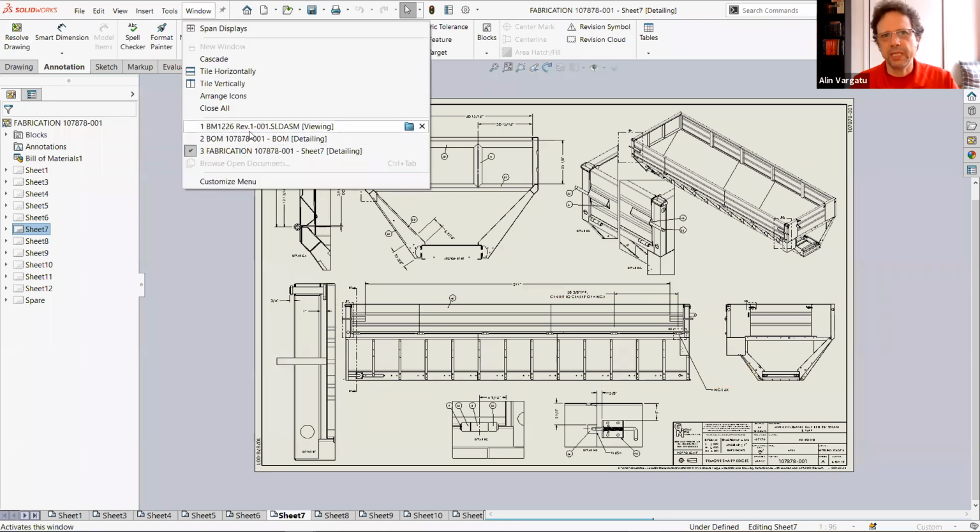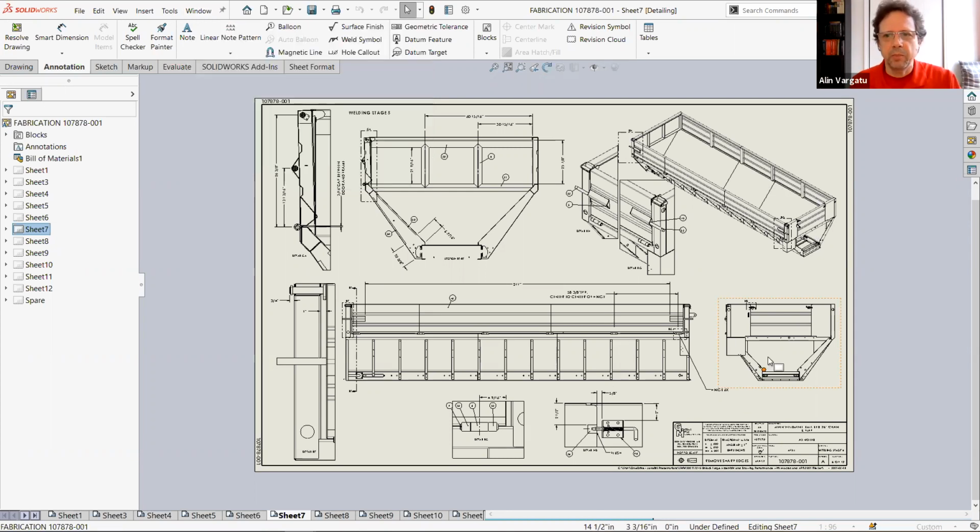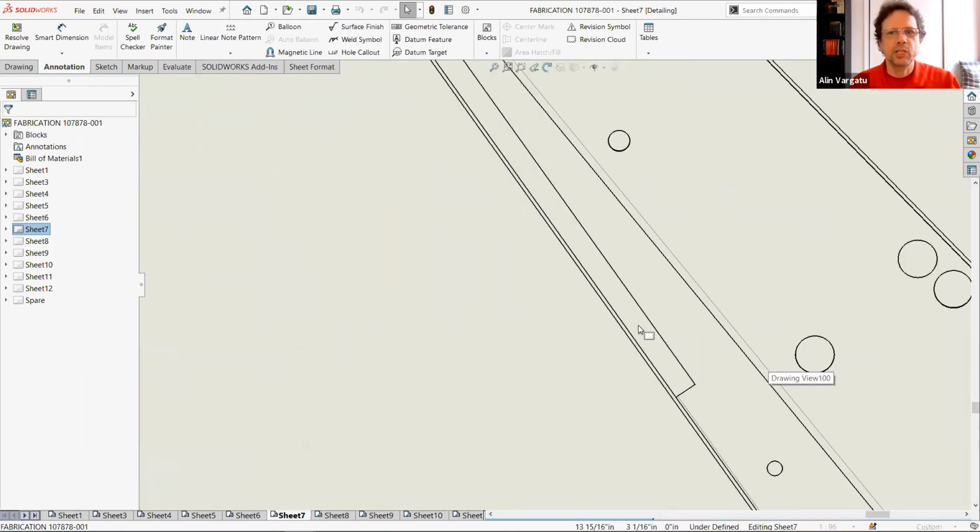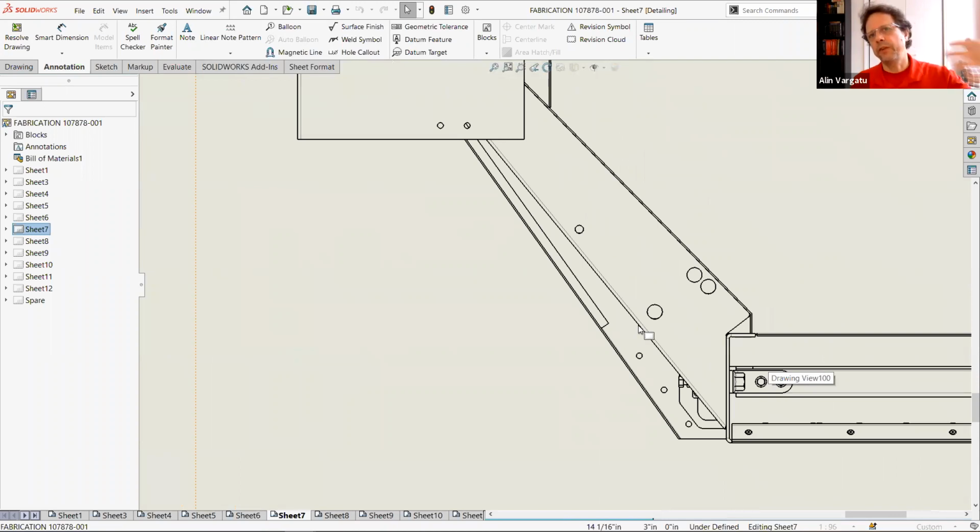So right now, even though you see the top level assembly, which is loaded in large design review mode, it really doesn't have the information of the drawing required. This drawing opened on its own, like you would open it in AutoCAD, let's say, a bunch of edges loaded there. But the cool thing about these edges, they are intelligent. They know to which faces, to which components they are attached.